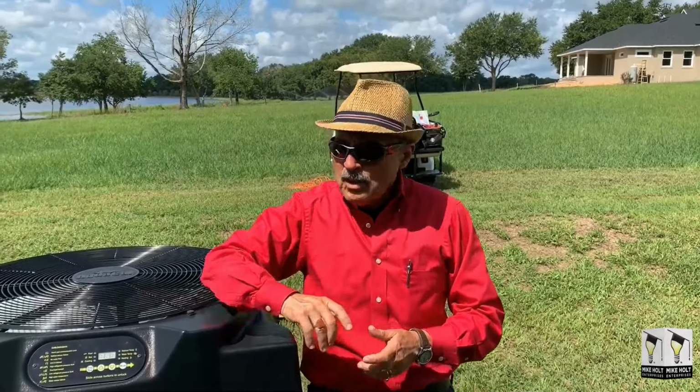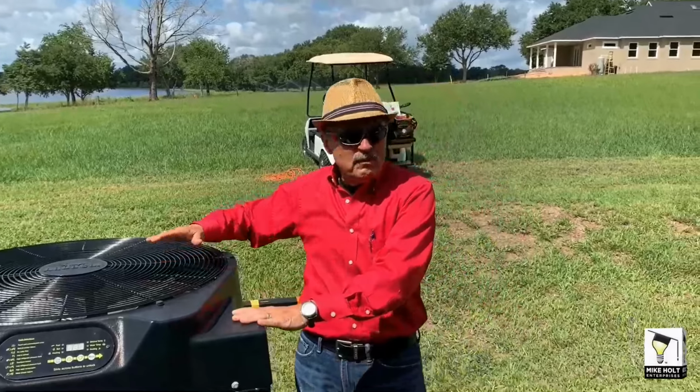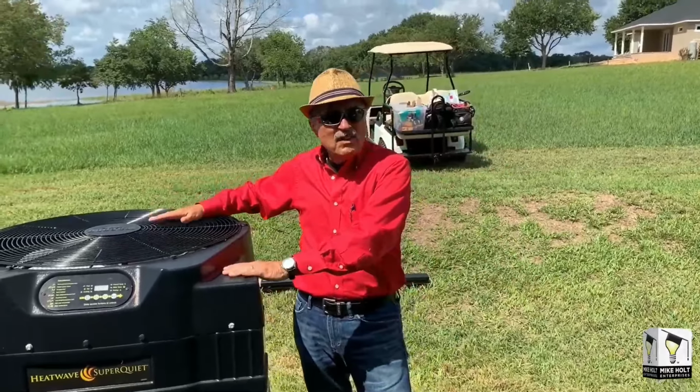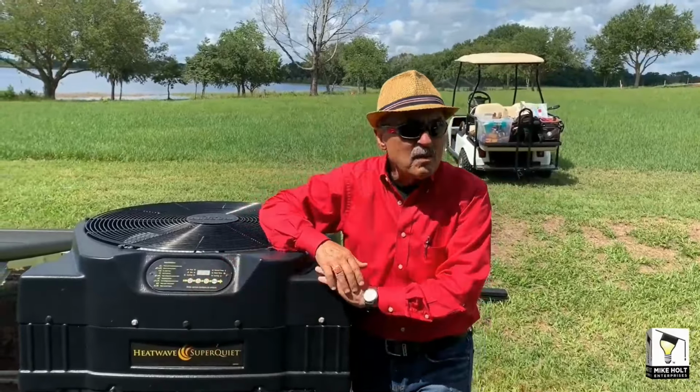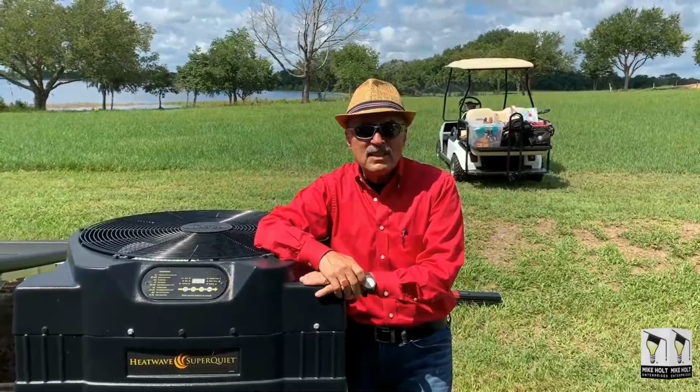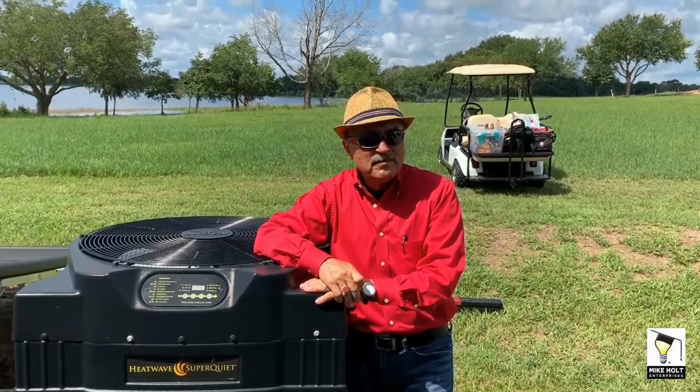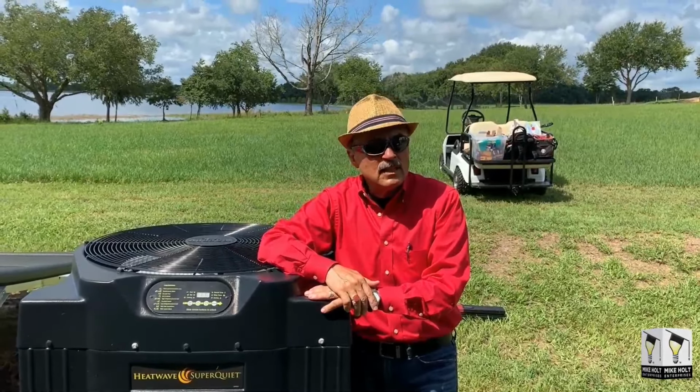The young boy got killed on the pole because he touched the pole, or he was in a voltage gradient, because they purposely grounded it. They purposely did not bring an effective ground fault current path because they thought grounding would make it safe. You okay with that, guys? All right, let's go back into the class and take a look at some more stuff. We're going to go right here to this picture. Ready?